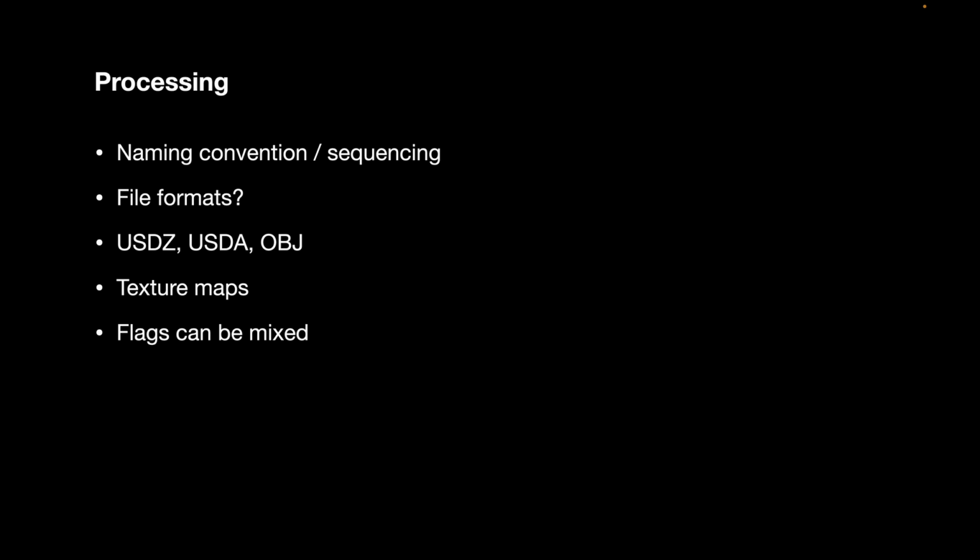You can combine them, and the software is smart enough to reuse the previous result. For example, if you generate a low resolution point cloud and a medium resolution point cloud at the same time, the low resolution point cloud will be created first. Then when the software is creating the medium resolution point cloud, the information from the low resolution one will be used. It doesn't have to start from scratch.